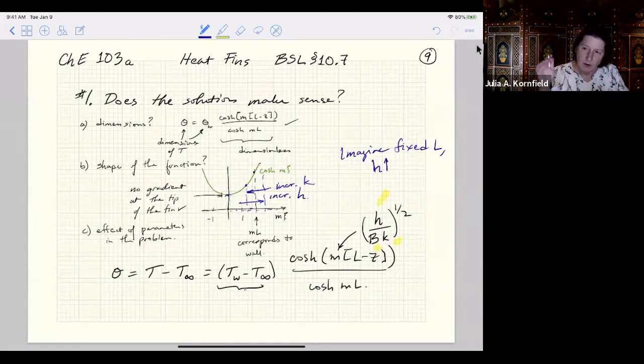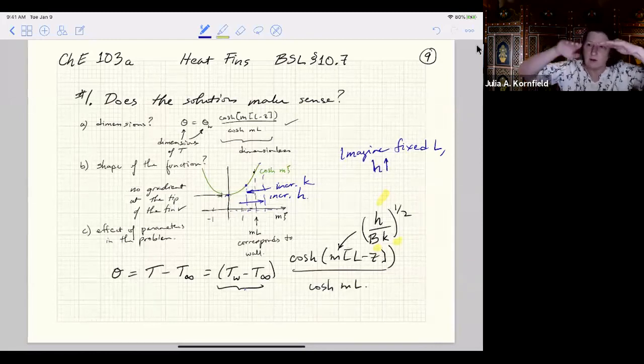So again, you can hit pause if you want a minute to think about why that would be. And then I'll blurt it out. So if I make the thermal conductivity higher, the conduction is faster out into the fin, and it keeps moving that heat out, keeps that temperature difference very small, because the higher the conductivity is, the smaller the gradient required to move that energy out.